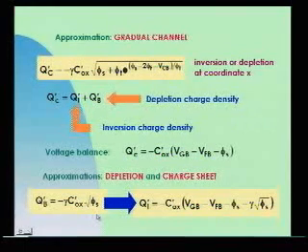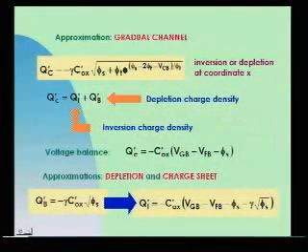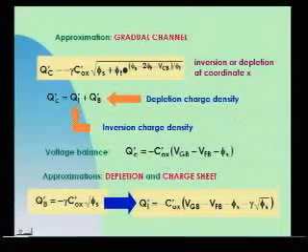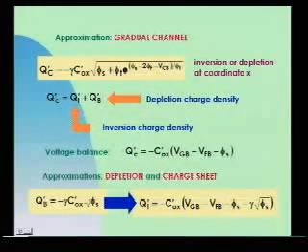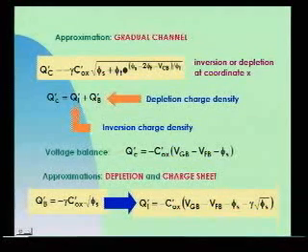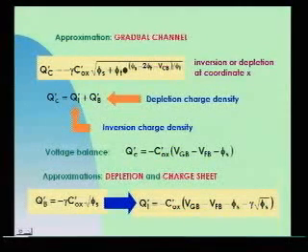It's the same potential at the top and at the bottom of the inversion layer, because the inversion layer is so thin that there's no voltage drop across it. It's an approximation, sure. It's the charge sheet approximation. I mean that the inversion layer is a sheet of charge.